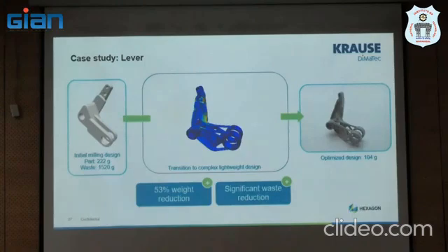So when it comes to the validation, that is a major input. It has to be taken care of. Because first, the optimization runs on the material characterization only. So when I start the optimization, I will give the CAD file, then I will define the material property, what is the yield strength, what is the Young's modulus and other stuff. So based on that only it does the optimization.